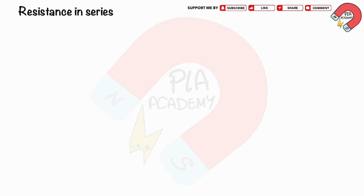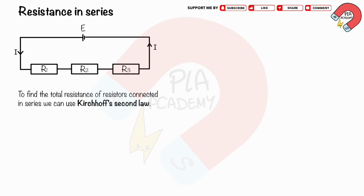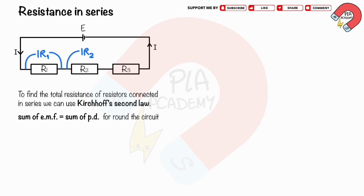Resistance in series circuits. The cell with EMF E and 3 resistors are connected in series circuit, as shown. The EMF E drives a current I to flow through a circuit, and passing through each resistor. To find the total resistance of resistors connected in series, we can use Kirchhoff's second law. The sum of EMF is equal to the sum of PD around a circuit. The PD across R1 equals IR1. The PD across R2 equals IR2. The PD across R3 equals IR3.